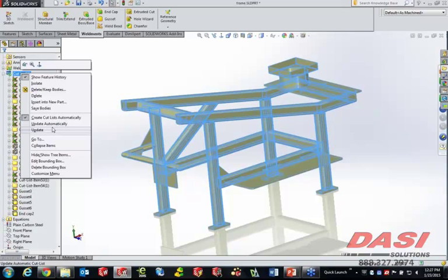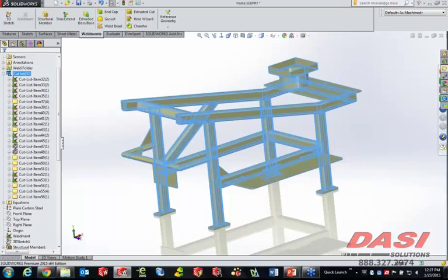Well, now you see very clearly that there is a tool called automatic update or update automatically. By clicking this, I'll never have to readdress this cut list again. Those 4 gussets at the bottom and the 1 end cap will jump into folders that match other geometry sizes. But if I add additional things, those will also automatically jump into these folders. So that's the first most important thing there.